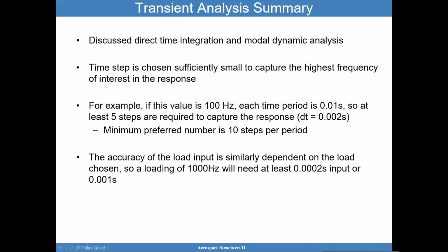Very similarly, if your load input is selected to be 1,000 hertz, please provide at least 0.002 seconds of input to make sure you're providing a sufficient amount of input to the model so that the model can respond properly to the inputs you're providing. If the inputs you provide to the model are too coarse, then you may introduce invalid dynamic responses that are really not existent.